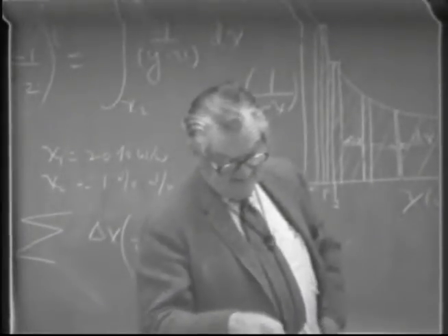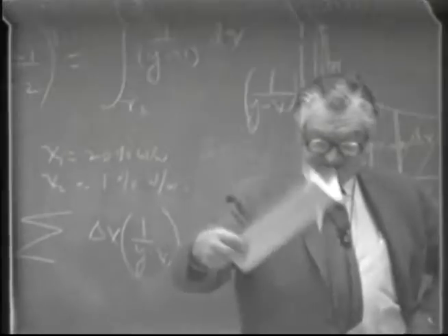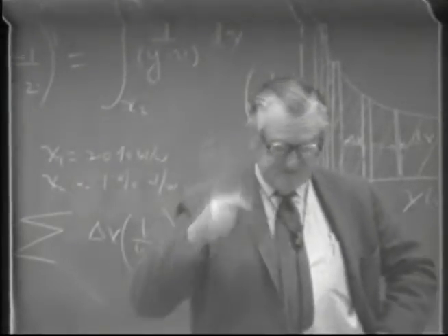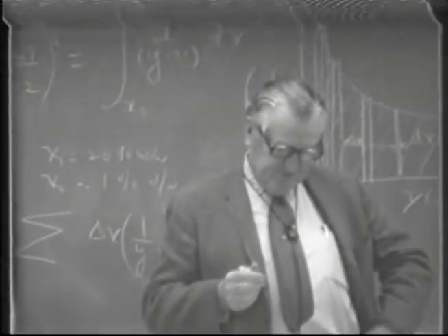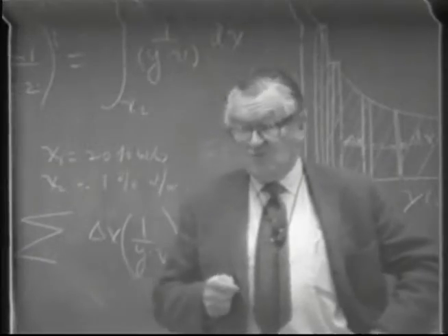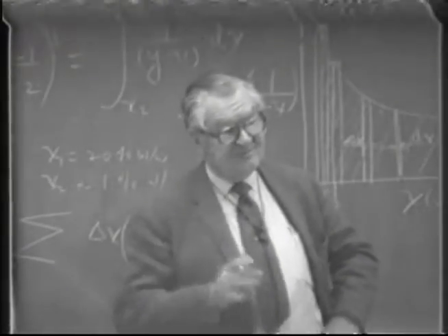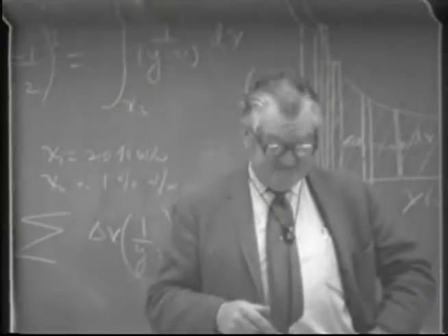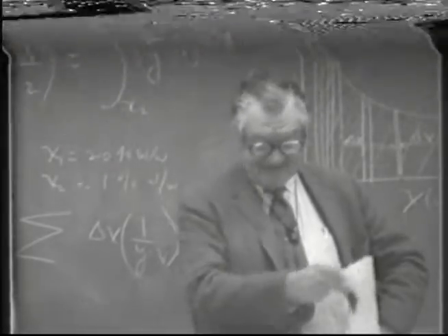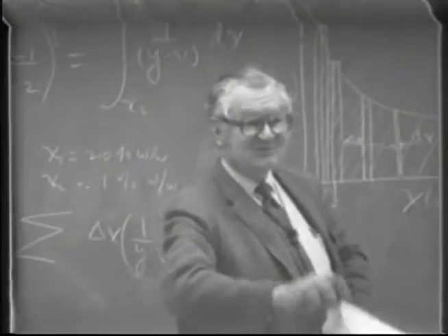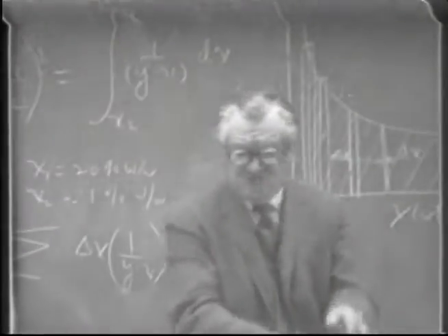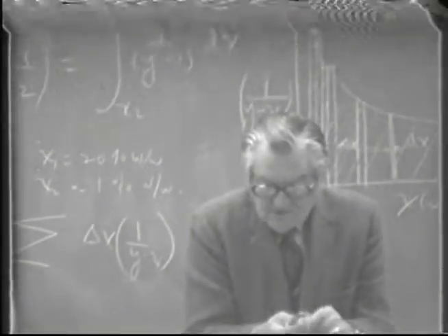And the rest of that last page here discusses a little bit about that. It should be something of the order of 16 to 20% alcohol, a typical figure for the wastewater leaving the decanter, returning to the column. So with that, unless there are some questions, we'll conclude our discussion about fusel oil separation and decantation.